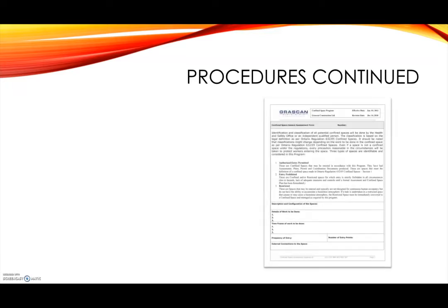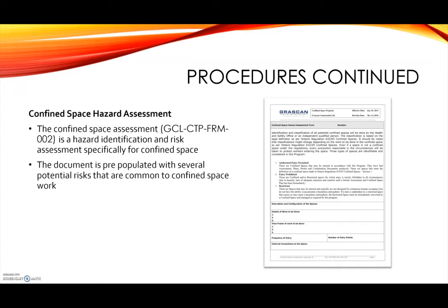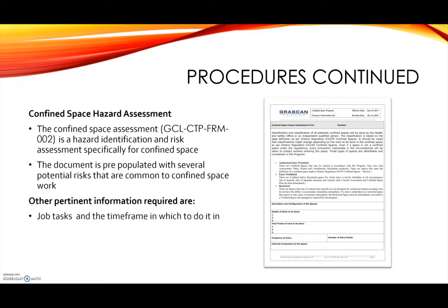Procedures continued. Confined Space Hazard Assessment. The Confined Space Hazard Assessment Form is a hazard identification and risk assessment specifically for a confined space. The document is pre-populated with several potential risks that are common to confined space work. Other pertinent information required are job tasks and the time frame in which to do it, frequency of entry into the confined space, and number of entry points.